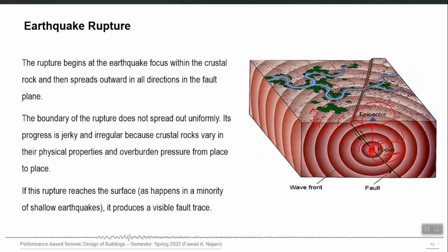So it's a shock of that rupture which reaches you first, and after that is the S wave, which is actually the transverse movement, right. For structures, mostly the S wave is more dangerous, right. The P wave reaches first because it has more velocity. So just like an explosion, first you experience its shock, right, and then you experience any of its other destructions, right. So body waves again have two types, P and S, and of them P is faster than S, right.